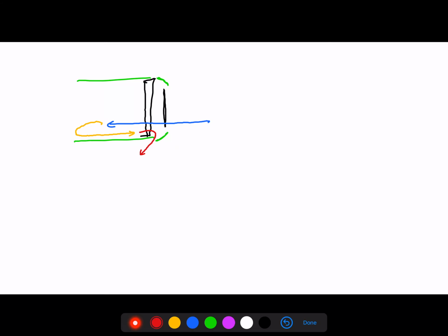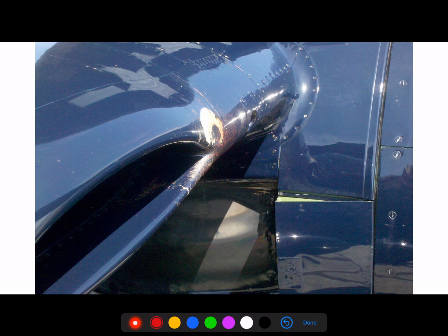It's very ingenious in the design it has, and it's pretty clever, but it serves as a nice segue to talk a little bit about the functions we have for being able to regulate oil temperature and thereby engine temperature of a reciprocating aircraft. What I want to take a look at next is a common device we see. One of the beauties of having an oil cooler is, especially in a dry sump system, we can locate it remotely from the aircraft, or rather from the engine.